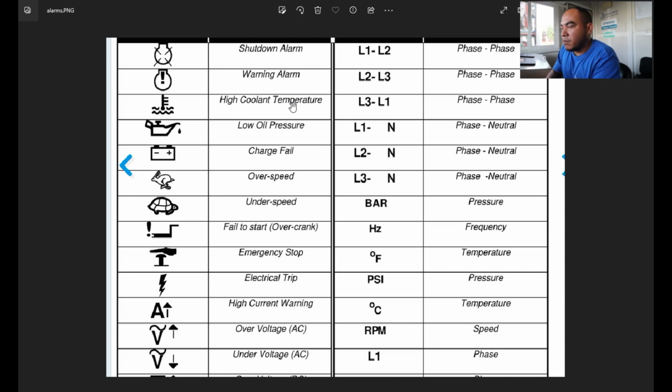Most common is a dirty radiator. There is some blockage in your radiator which you need to clean. You have to pressurize it to remove the dirt, so that if the fan is moving, it can easily remove the heat.